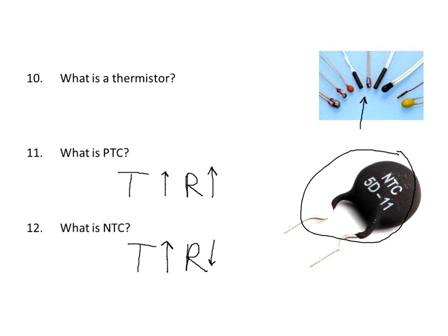But what kind of electronic devices are PTC? Well, MOSFETs are positive temperature coefficient. I don't know if you've ever listened to a high-power audio amplifier. Maybe you're in somebody's car. A lot of them are MOSFETs. MOSFETs will cut back on their conduction when they get hot. So they kind of protect themselves. So they are positive temperature coefficient.